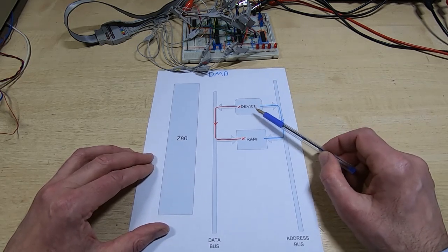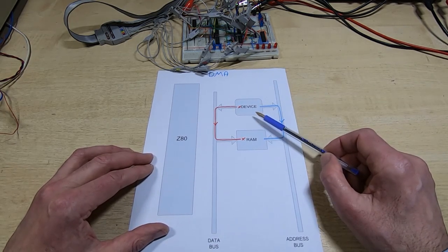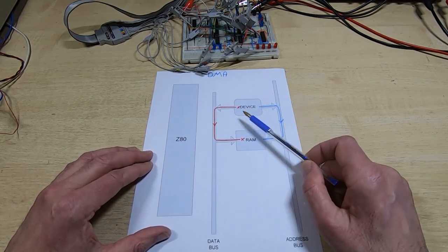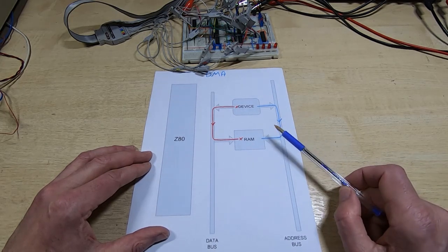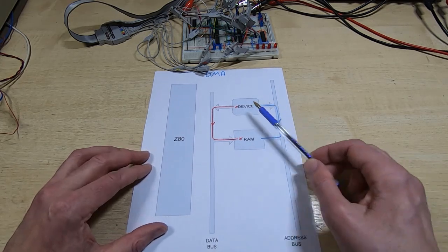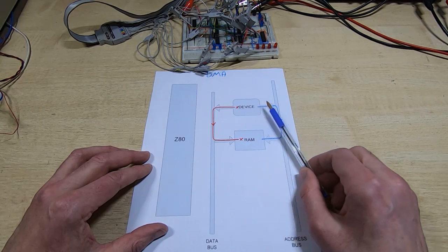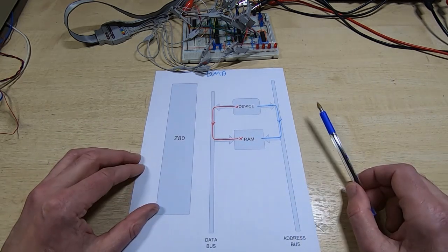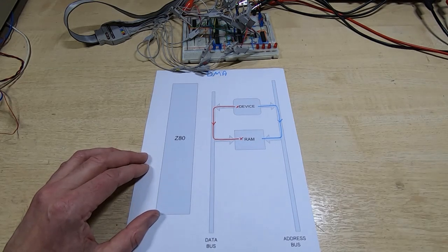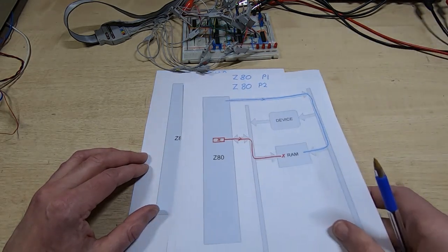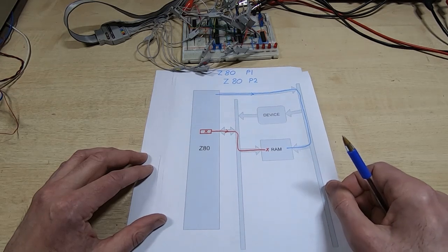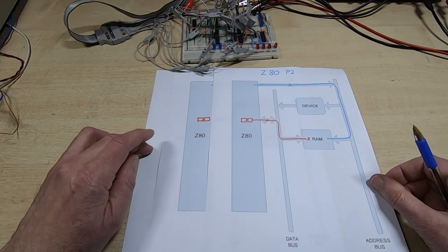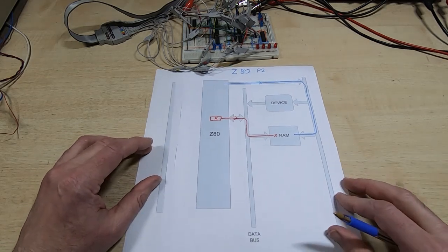Now, to make this work, you do have to add quite a lot of electronics and circuits to the design, but as you can hopefully see, it's worth the effort because it greatly speeds things up. For example, a transfer like this is only going to take, in our system, less than a microsecond, whereas doing it like this takes maybe 20 or 30 microseconds per byte. So this is probably 25-30 times faster using DMA.